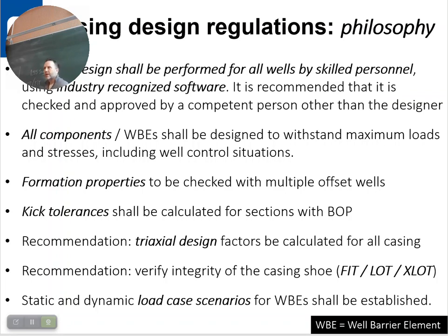That could be the thing, yes, definitely. But if we are in the casing design class, what do we do? So on the board here, in the middle of the slide almost, kick tolerance, right? The kick tolerance, the FIT at the shoe and the formation strength there: the kick tolerance is very much affected by the strength of the formation, the weakest part under the shoe.